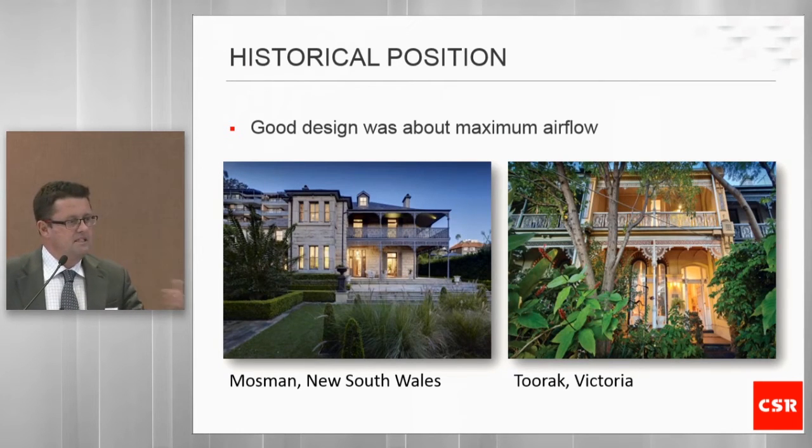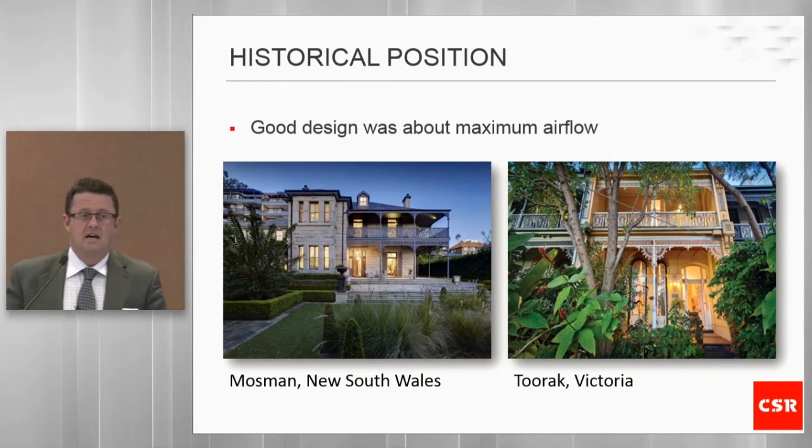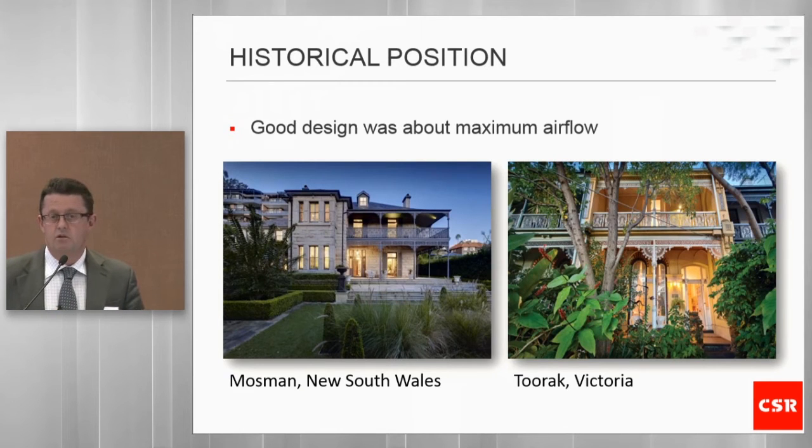So what that means is that there were gaps and cracks in walls and around doors and openings, which actually was promoted. There were vents in walls, and these vents allowed smoke to egress because they used kerosene lanterns in the old days before electricity, and they used smoke fireplaces to warm the houses. As Scott said, they would have been zoned off into tiny little spaces, so you would have only heated a very small component of the house, and the rest of it would have been unheated.